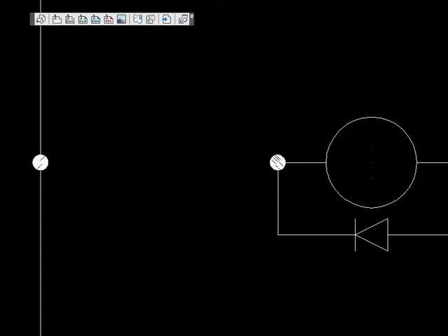The thing about a block is it also provides for consistency. If you draw it one way once and you save it as a block, it's going to be drawn the same way a second and third time, from drawing to drawing, from job to job, from year to year, if you desire to do so. The neat thing about dynamic blocks is it takes that block concept in AutoCAD to the next step. What they've done with AutoCAD, and I think is a very useful and productive tool, is it allows you to embed modification tools into that block. You have the ability to flip the block or mirror the block. You can rotate portions of the block, you can stretch it, you can scale it, and you can move it.